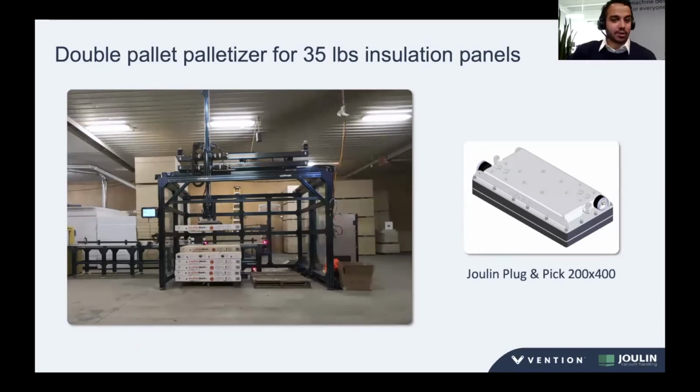And so here's kind of like the most common example that we see of a palletizer. So it's the double pallet palletizer. Like I mentioned, it's really easy to justify going for that slightly larger machine in terms of how it fits into operations, obviously if you can afford the floor space. This particular case is for a slightly more unique product. So these 35-pound insulation panels. So actually more of a kind of wooden surface on the top there, not really regular. Suction cups kind of struggle with this kind of surface.